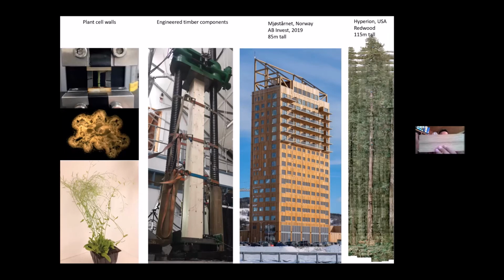You can see very thin veneers of beech wood that are compressed all in the same direction to produce this sort of material. And the advantage is because it's a highly digitized process, you're getting rid of knots, for example, and weak points. And this product would be 4 to 7 times higher in strength than just sawn timber.